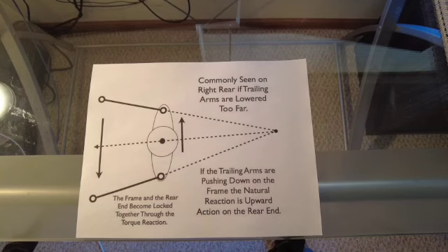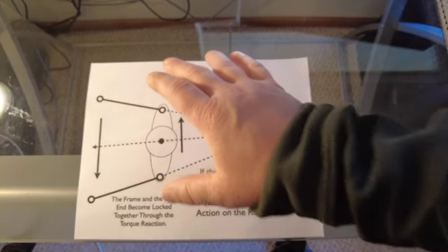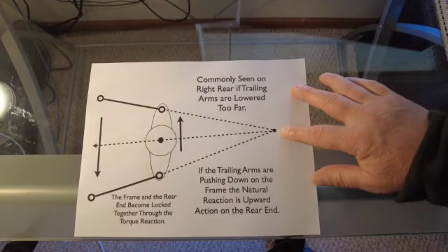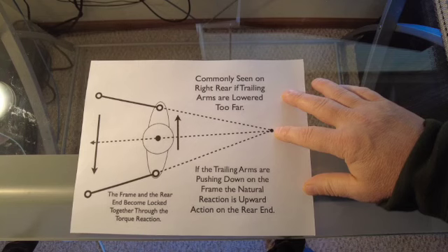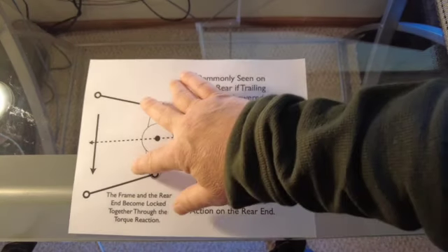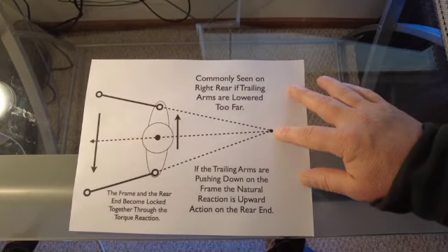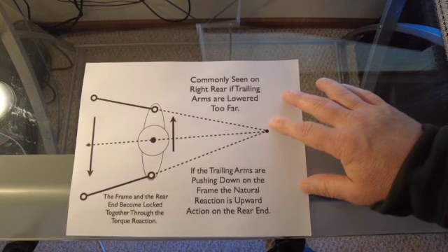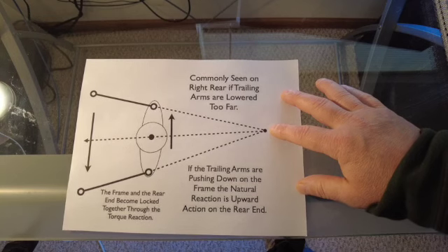Now let's just say, for instance, that your ride height lowers on the right rear a little bit. Look what happens to this point. If you take load out of your right rear, you're lowering the ride height. This point will move up and you won't get your drive angle and your drive rod on the right rear as you used to have. So that's why it's really important to maintain a ride height on the right rear, more so than a smash number.